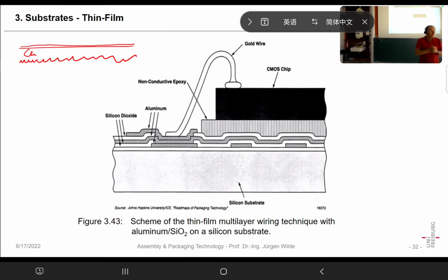But on the other hand, only the top side is smooth, but typically such a signal, as we have eddy currents, they would go somehow around that conductor, and in that way the damping is very high. So we want to have very smooth conductors.